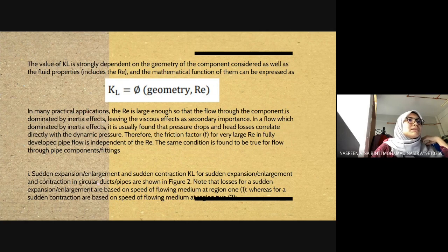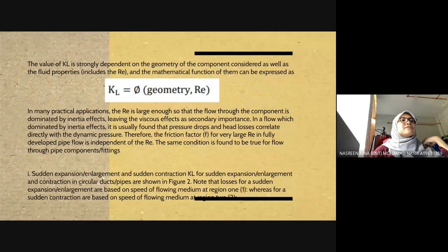HLT is the total head loss, HL is the major losses, f is the coefficient of pipe friction, which is dimensionless, L is the length of pipe in meters, Di is the internal diameter, V for HL is the speed of the flowing medium for the tested pipe, HLM is the minor head loss, and V for HLM is the speed of the flowing medium.